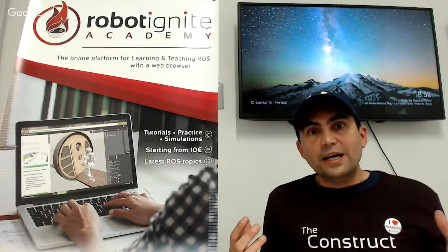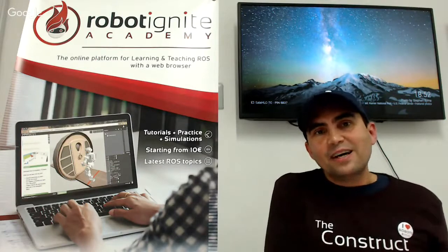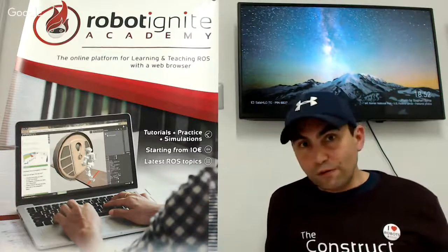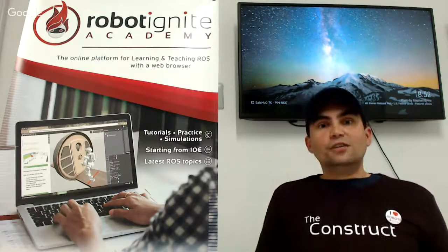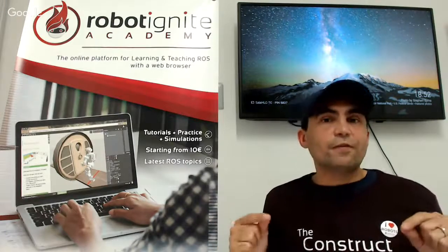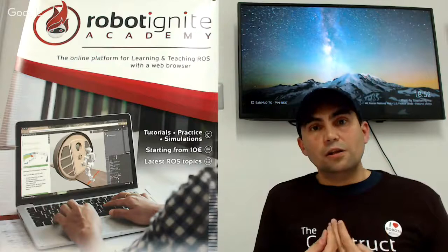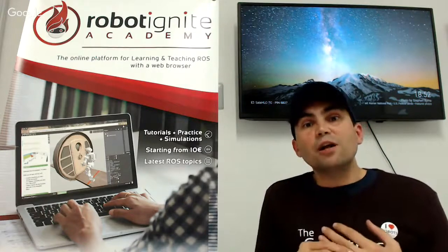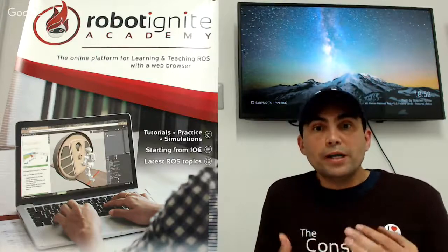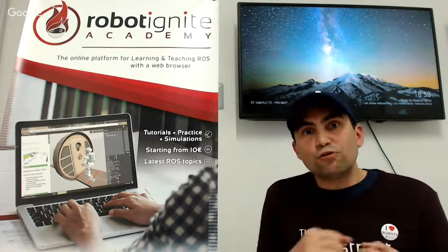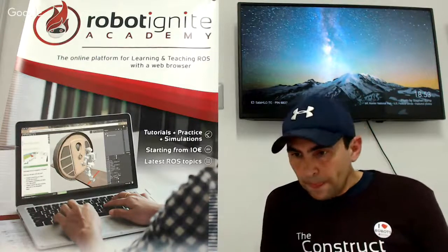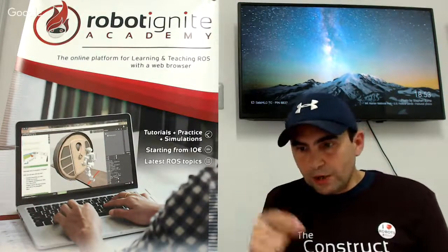Then, if we have 768 rays, like a Hokuyo, for example, that increases the number of states a lot. Then learning the policy is a lot more difficult. It will take a lot more time, because the robot has to visit many more states in order to create a map of the possible decisions that it has to take. It's a very good question, by the way, Scammy-Ambas.